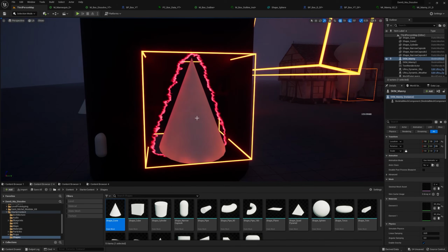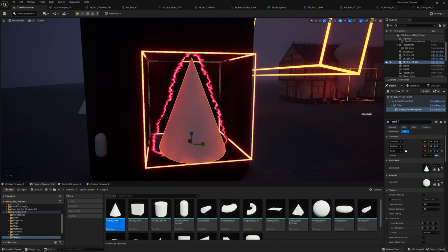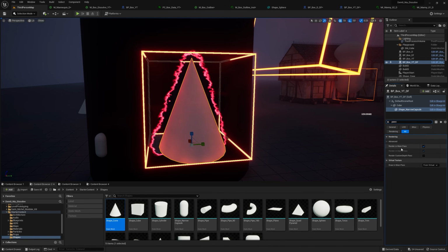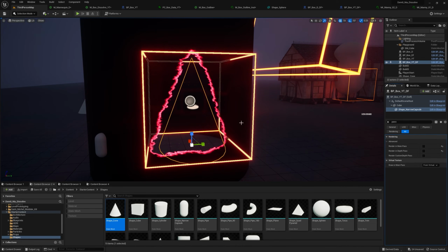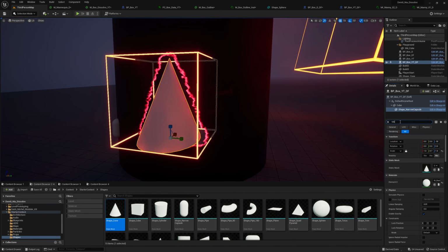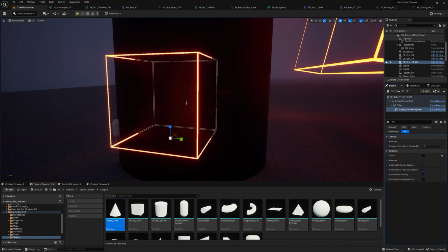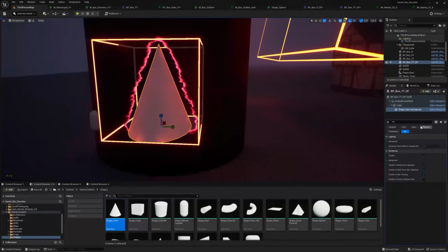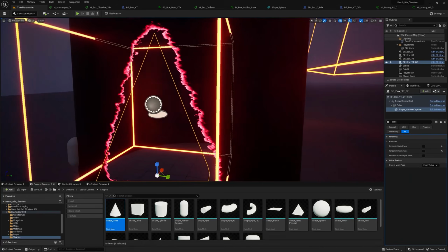And here if you want to hide this mesh, you can select the mesh and type in pass, and type in render in main pass and untick this also, so it is hidden. If I just untick visibility and make this false, it will disappear because the mesh has to be visible in order for this to work. So I have to go to the main pass and just disable that from the main pass, so it won't be visible.